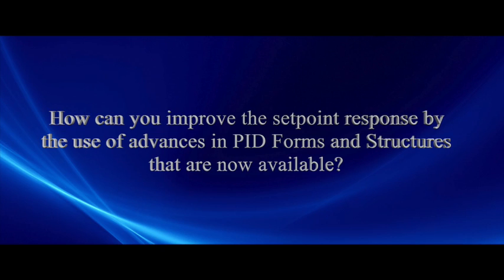And they don't care how long it takes to get to set point, because in the new biological processes the batch takes 10 days. So if it takes 15 or 20 minutes more to get to temperature set point, who cares? They're not going to change batch times anyway. So in terms of set point response, you have a lot more options with the newer controllers.